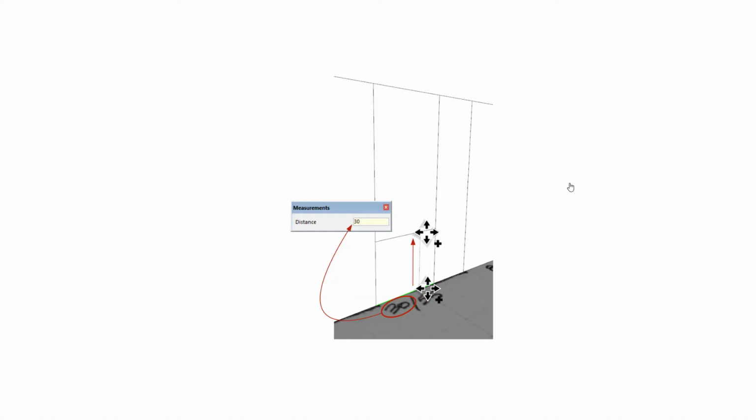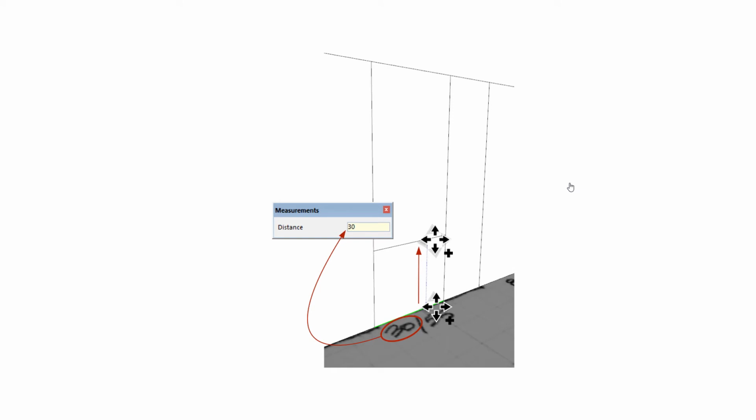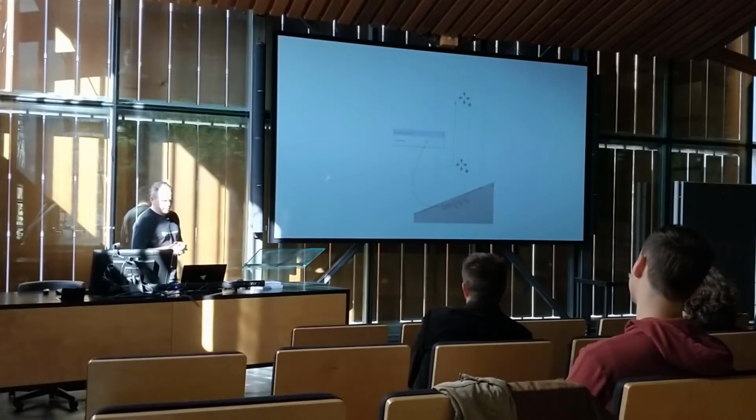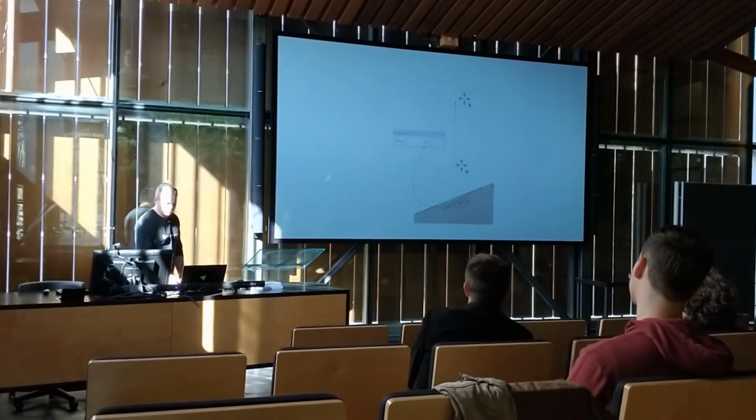So once you've gotten to that point, now you can start doing your window and door openings. For instance, here we've got our window height, sill height, window height. So we're just going to copy that line up by 30 inches, and then we're going to copy it up again by 55. After I've extruded all my exterior walls, I just run around the outside. It's like a factory production line. I'm just knocking this thing out, doing the work that's presented in front of me.